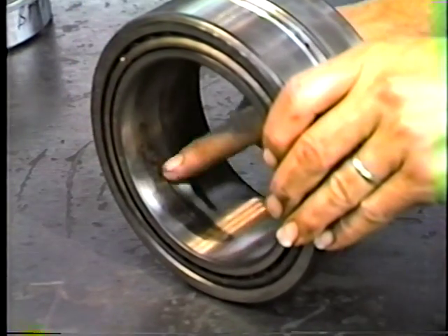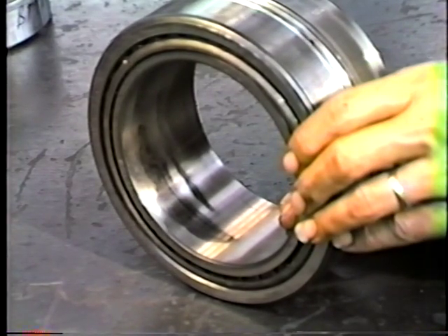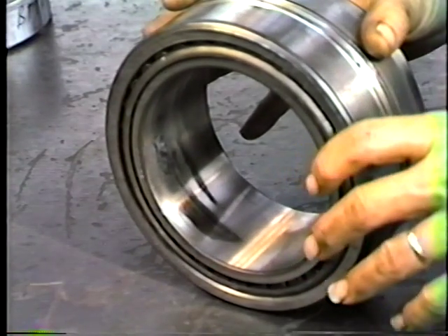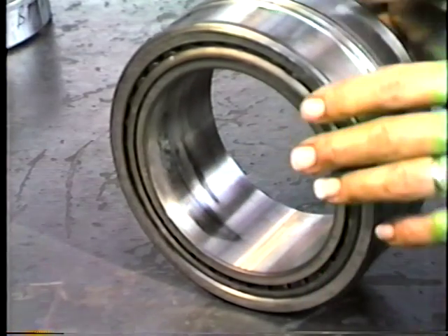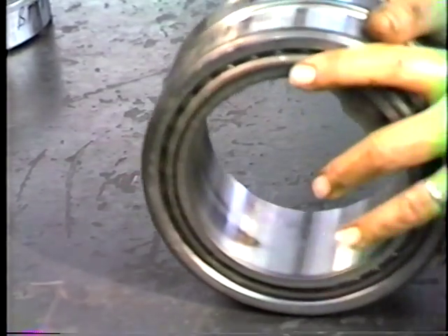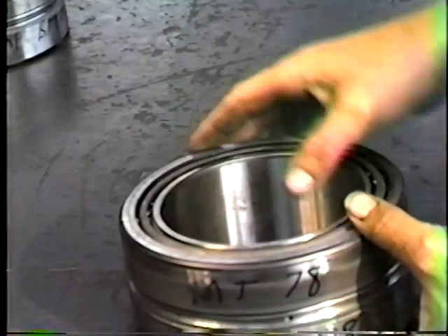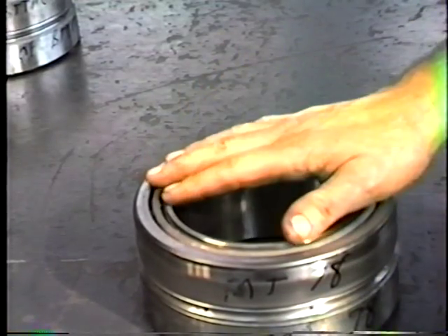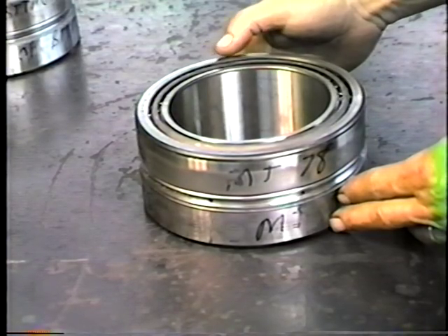See that inside there now? This bearing came out of the journal, the first one that we rebuilt for Comco. It's number 1 journal. It's got Mobil Temp 78 grease, and apparently has more wear than the original bearings with the SP3. Move it back a little bit. Stay in the picture. Okay, I can see Mobil Temp 78 on there.